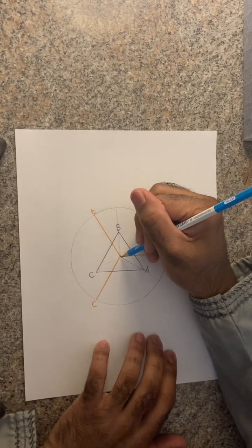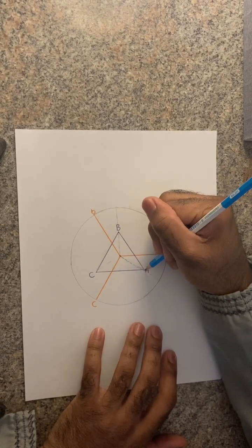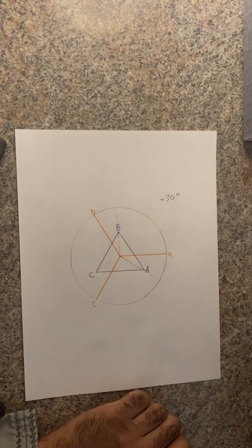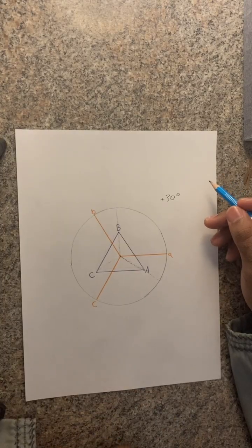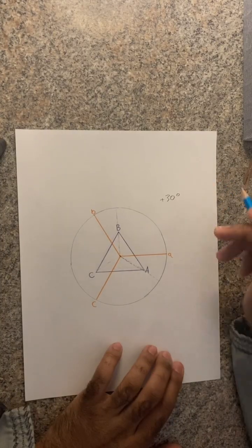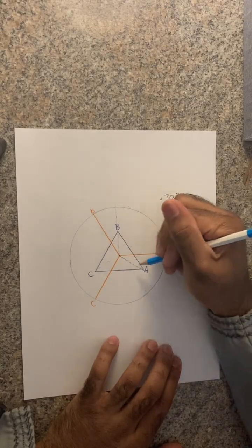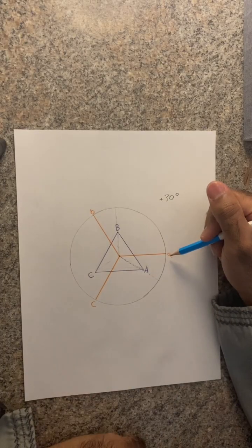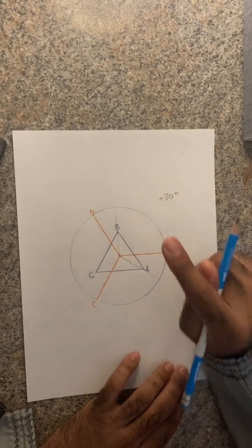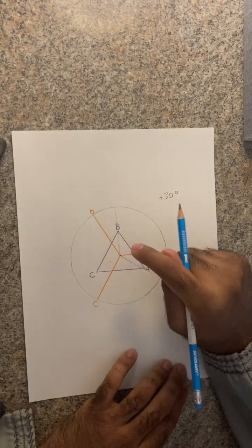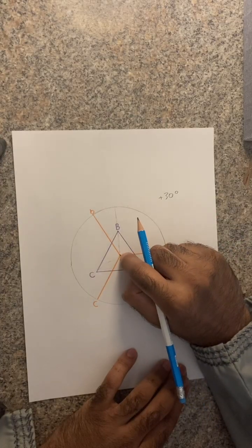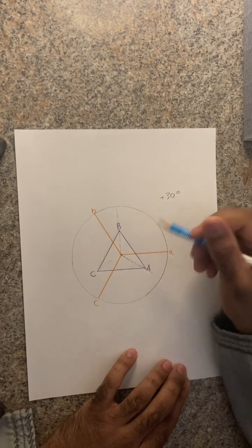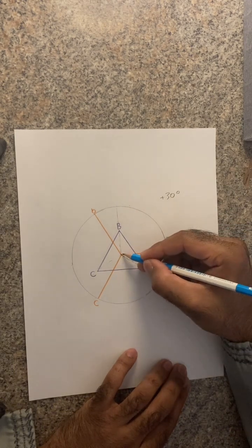Technically speaking, this is a line to neutral voltage. This is a line to neutral voltage. This is what angular displacement is referring to in reality. It is referring to the line to neutral voltage of the delta and the line to neutral voltage of the star. The line to neutral voltage in this instance is, if you will, imaginary. The imaginary line would be constructed to compare the delta with the star.